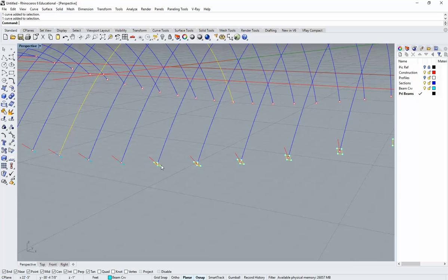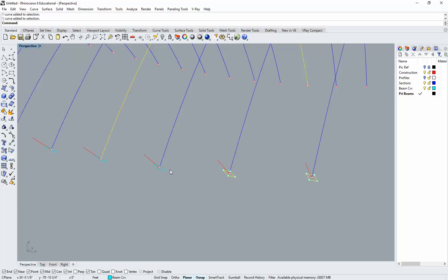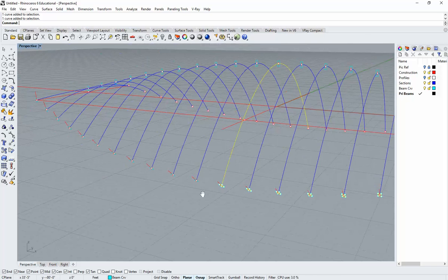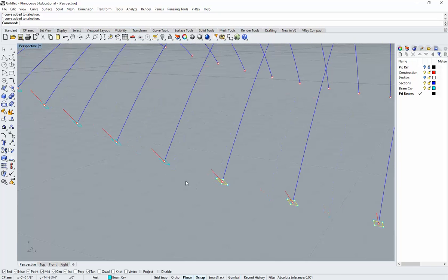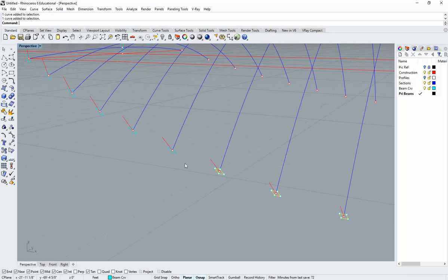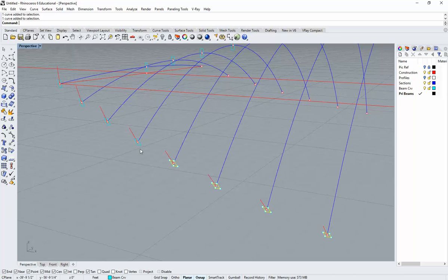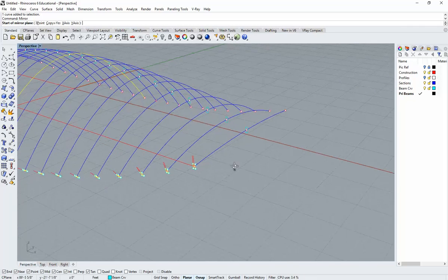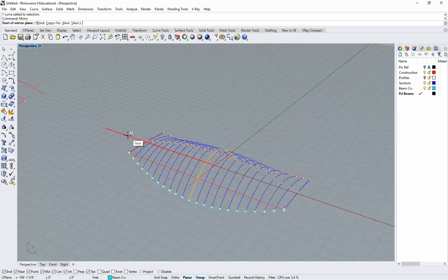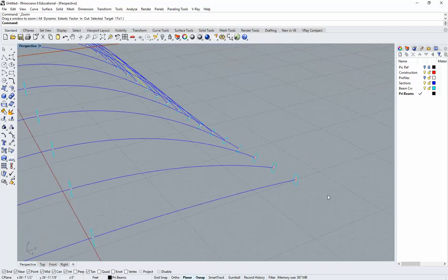So you want this on the other side, so you can set all 3 section curves when we do the sweep command. And that'll be easier to run the 3D work out. So I'm going to click on all these, and I'm going to mirror that around my mirror line. Remember this? Click them over here. Okay, and there we have it. So those are ready to go now.